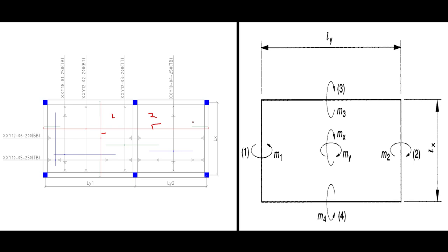In detailing, there is something we call calling out the reinforcement. We call it the call out. The call out shows the way in which the reinforcement is going to be arranged on site. It is not possible for us to start drawing all the reinforcement that you have. Let's say, for example, the total number of RX in this slab is 20. Then if we start drawing 20 bars, it will look cumbersome and it won't be readable by the site engineer or the end user. So in that kind of situation, we use the call out.